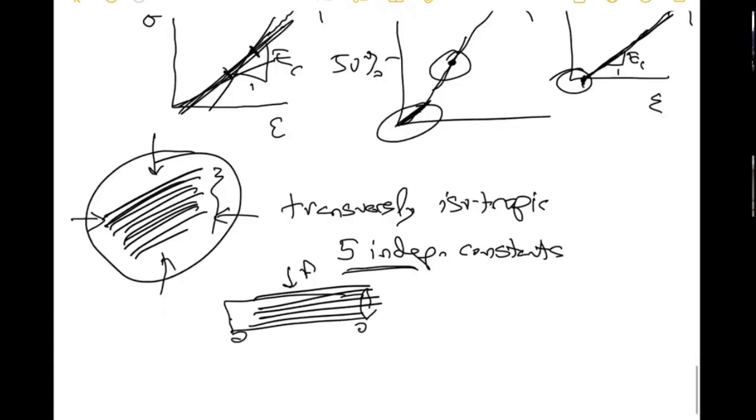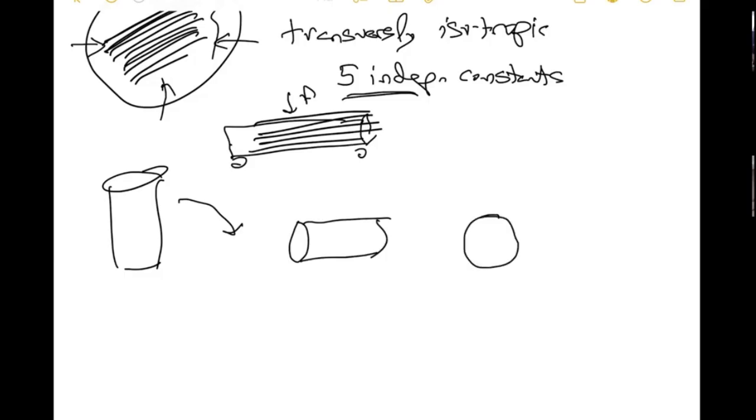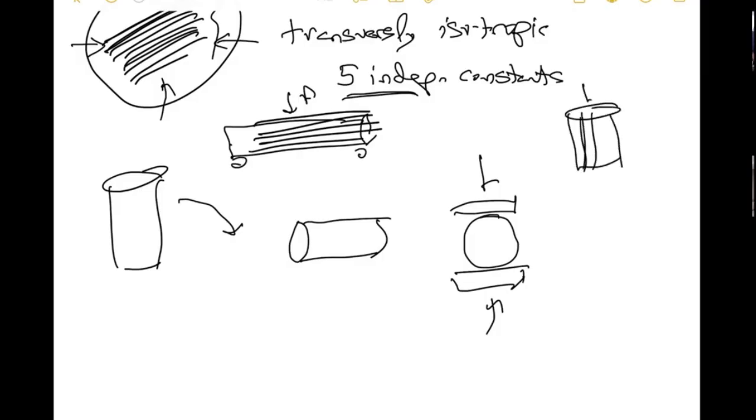But someone figured out at some point that if you take a cylinder and if you turn it on its side so that now it's like this, and I'll rotate it again so I'm just looking at it like that. And now if you take 2 steel plates and you push it, now this is a complicated boundary value problem. This is not a uniform stress field. If I have this case, the cylinder, and I push it, I get uniform force chains. Everything's the same everywhere. In this case, you don't. It's complicated. You're just loading a point here.